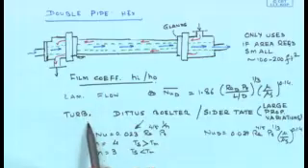But whatever I have described here refers to flow inside the tube. So, what is to be done when you have flow in the annuli? The common practice is you find out the hydraulic diameter for the annuli, and then use all these equations depending on whether you have laminar flow, turbulent flow, or significant variation in property. All those correlations are equally applicable for the case of annuli as well, provided you replace the diameter by the hydraulic diameter. Then all these relations can be used.